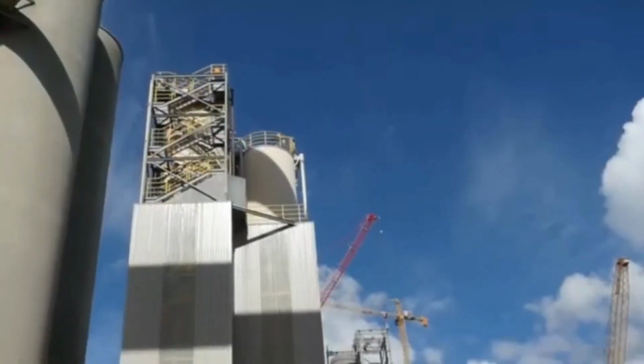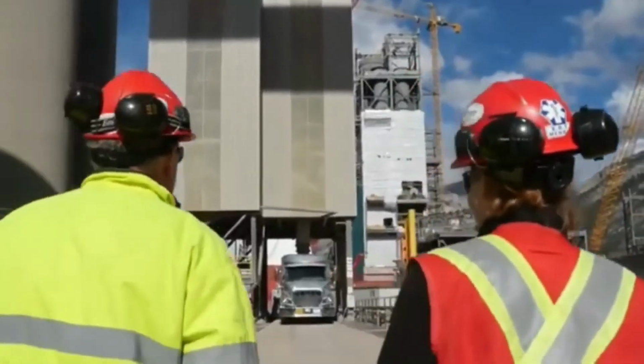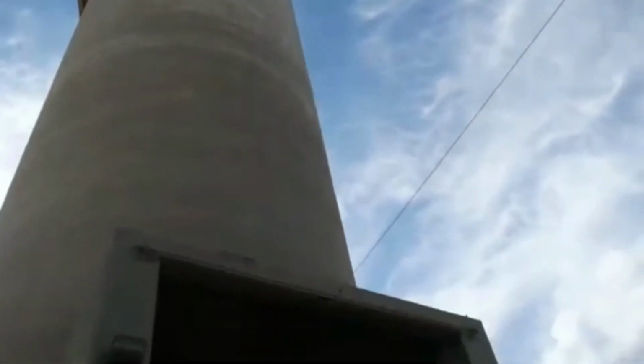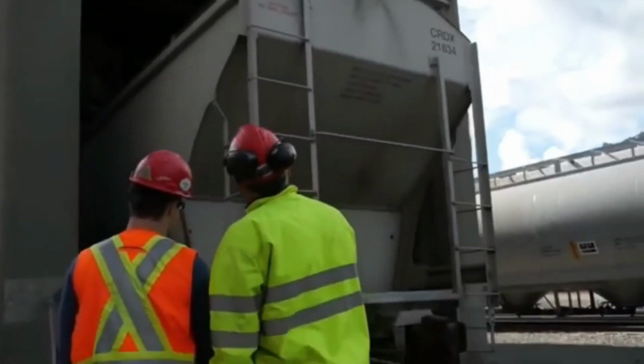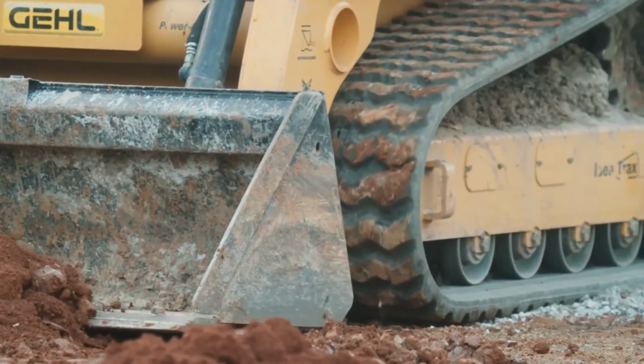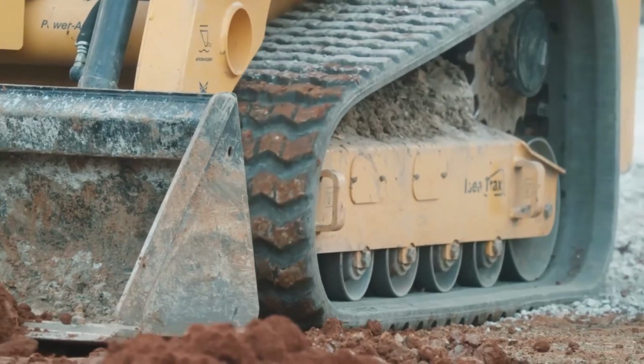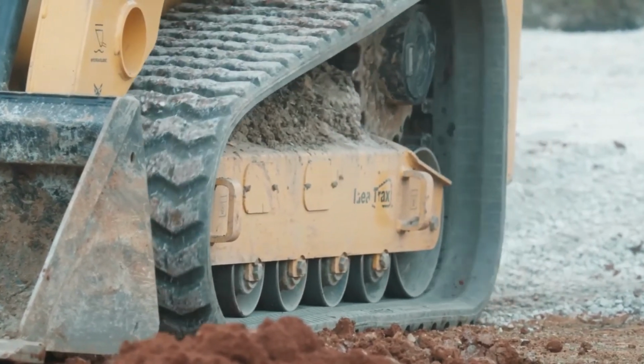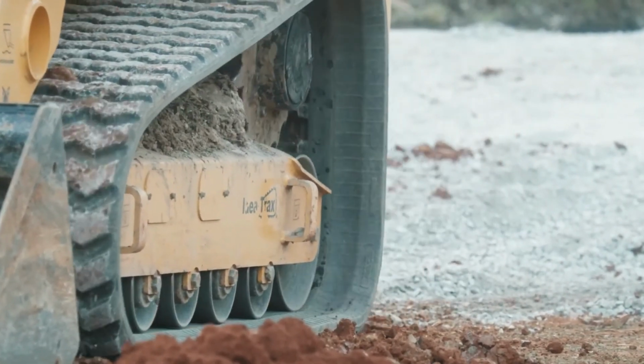When the Portland cement is mixed with water, it forms a paste that becomes firm, or sets, in about 2 hours. After the paste sets up, it slowly becomes much harder. The setting up and the hardening of cement paste is caused by the chemical reaction between the cement and the water. This is called hydration.